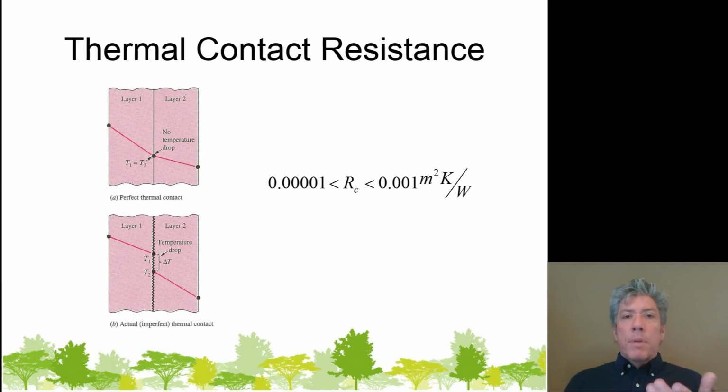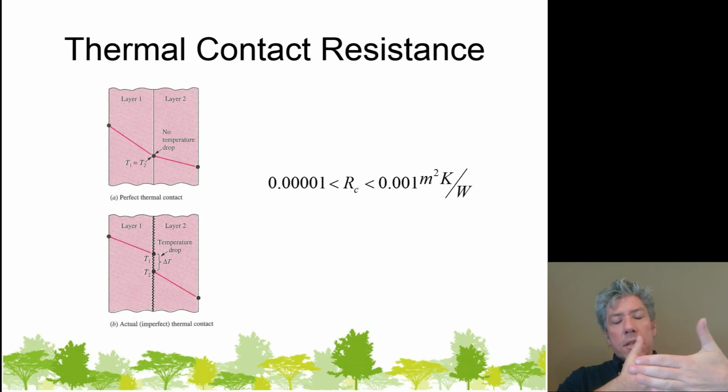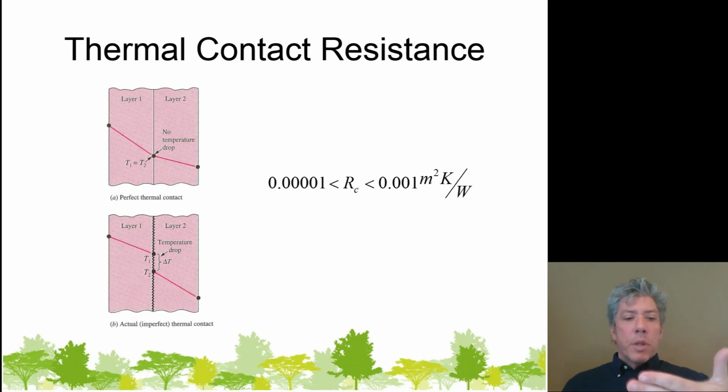The purpose of making it out of aluminum is so that heat can flow out of the LED through that aluminum and to the back plane of this TV, which is made out of metal. When I put it all back together, I put a little bit of heat sink compound behind each LED on the aluminum strip, so that when that aluminum strip touched the back of the TV, the LED on front could get its heat through. So I increased the contact between the back side of those boards and the back side of the TV.